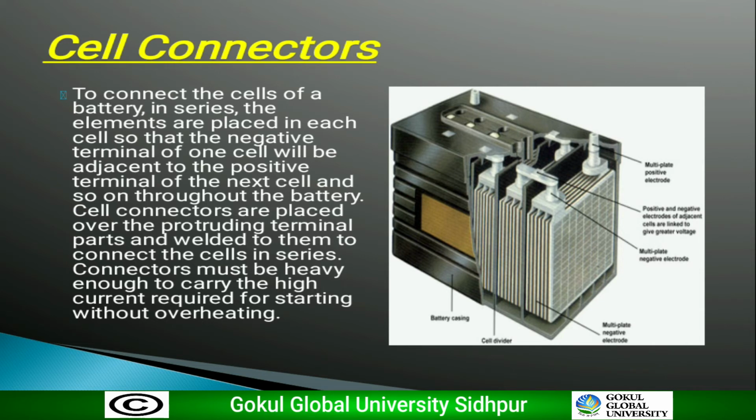Cell connectors are placed over the protruding terminal parts and welded to them to connect the cells in series. Connectors must be heavy enough to carry the high current required for starting without overheating. This connector must be heavy to carry high current during the vehicle starting.